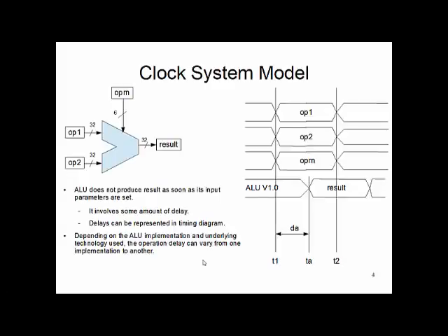or arithmetic logic unit, and the schematic diagram looks like this. The functionality of this specific piece of hardware is that we give this hardware two operands, like 32-bit binary values, and an operation code encoded with 6 bits, and this produces a result in terms of a 32-bit result value.